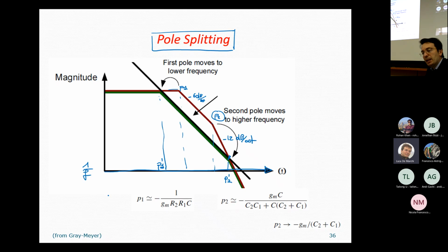When we have a negative zero, in terms of phase, also we have a sort of compensation, in the sense that the pole generates a phase loss, while the negative zero generates a phase gain. Okay, so at the end of the day, at very high frequency, we have a flat gain curve and a flat phase curve placed at 0 degree.